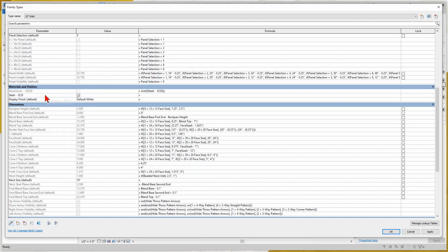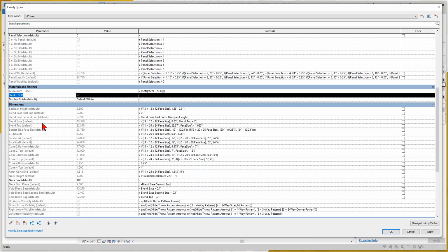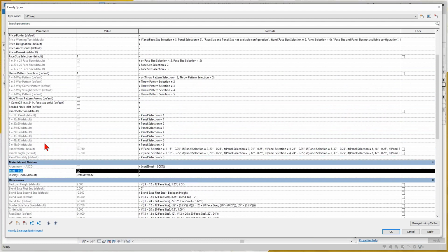But whenever you're going from instance to type, you're generally fairly safe as long as your type value is driving instance properties. Going in the reverse can be tricky. In this case, it was safe. It didn't have any problems because all the other parameters were instance already anyway. So it was real easy to convert this.